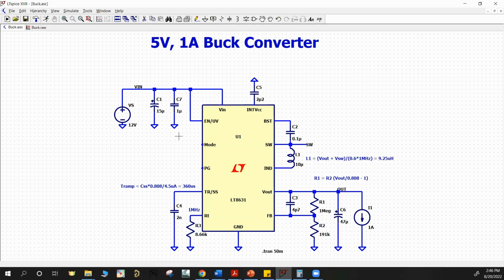Basically, what we have here is an enable pin, which you can think of as a switch. If this enable pin is pulled high, this switcher IC will be on all the time, but if it's pulled low, it will always be off. So usually, if we're not using any microcontroller, we just connect it directly to the high voltage side, and this ensures that this IC will always be on when there is a supply.